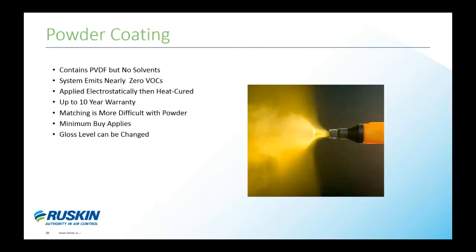Similar to PVDF finishes is powder coating. However, powder coating does not require solvent, meaning this coating system emits nearly zero VOCs. Applied electrostatically and then cured under heat, it offers good protection against the elements and comes with up to a 10-year finish warranty.